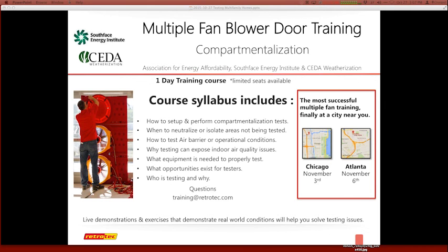There was one question here about the volume and housing calculated with or without a false ceiling. So I was trying to answer that question. I'm assuming it's based upon the standard, but you should include the entire volume. Yeah, we're really looking at the volume to the air barrier, which is either inside the wall or on the wall, so the wall that faces outdoors.